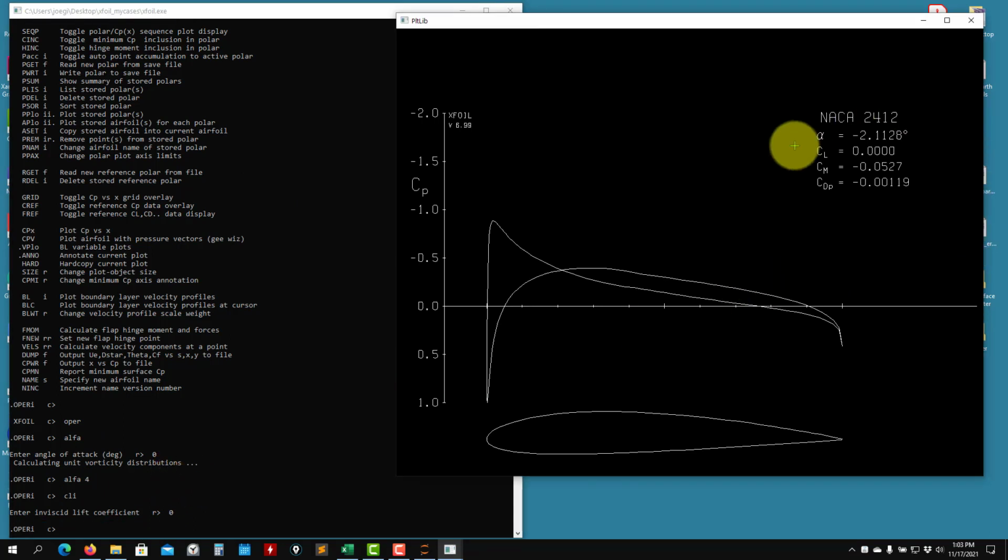And now this is your solution. Okay, so CL0, you have it at something about minus 2.11. So this is the basic inviscid computation. We are more interested in the viscous one. Adding over this panel solution, we're going to add a correction, a viscous correction.